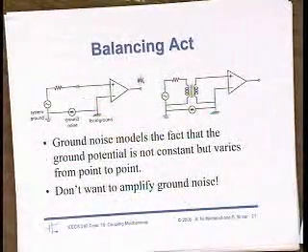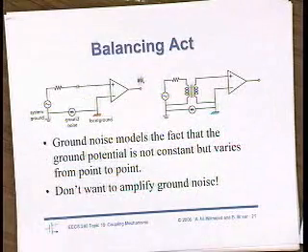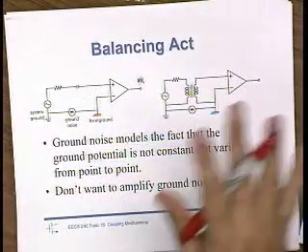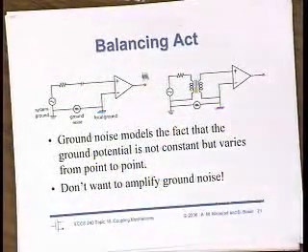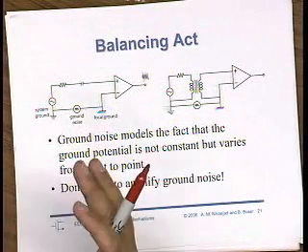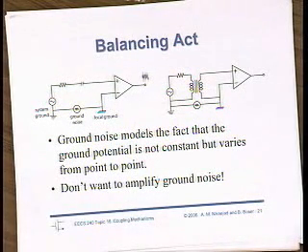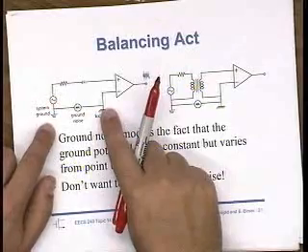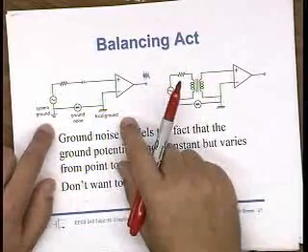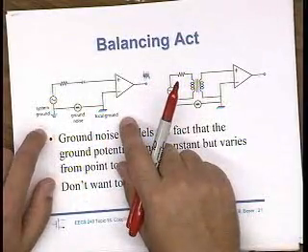The fact of the matter is, though, that if you build things, you're going to end up with multiple grounds. It's just unavoidable, right? You'd like to just have one ground point and then very well controlled ground connections to everything else, but in reality, you're going to have situations where either you're working with someone else's board where they've got multiple ground connections, or you just have to make multiple ground connections. And whenever you have multiple ground connections, always be aware that there's all these loops in your ground, unintentional loops that are picking up noise.